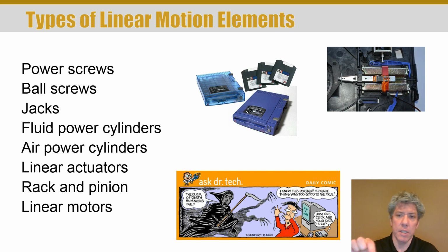Anyway, there was a head on the top and a head on the bottom, both for reading the magnetically stored information on the upper and lower side of the disc. And if it couldn't read a Z-track, which was pretty common because the Z-tracks were overwritten so frequently because you're always changing files, and so where each piece of each file is located is constantly moving around on those Z-tracks. Well, eventually all four of the Z-tracks would wear out, and so the heads would go to the Z-tracks, try to read, and slam, and it would click.